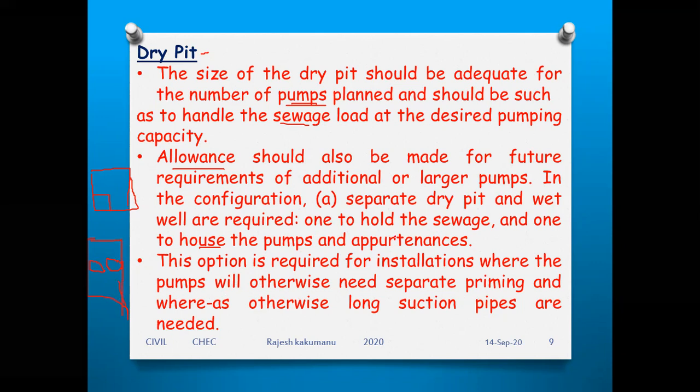In the wet pit or wet sump, you are holding the sewage, that is, you are holding the waste water. In the dry pit or dry sump, you are placing the pump and the other appurtenances. Appurtenances means the manholes, the valves, the other pipes, everything.